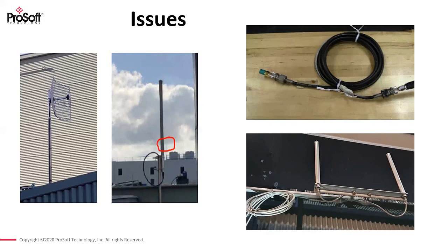So if you can picture yourself in a room and we're having a conversation, and there's about 4 people around you, and they're also talking to you as well while you're trying to listen to me, it's very hard. And it's the same sort of thing with the radio. The Omni antenna is going to pick up all of the radio signals around it, not what you want it to pick up, but everything else. So interference for the radio. Much better to use a directional antenna if it's just point to point.